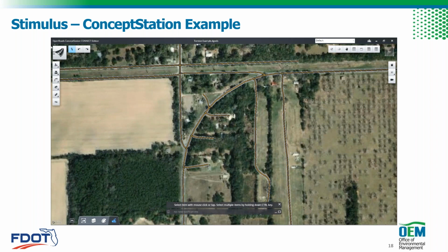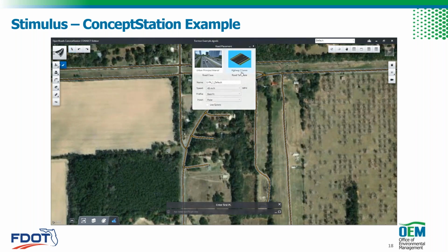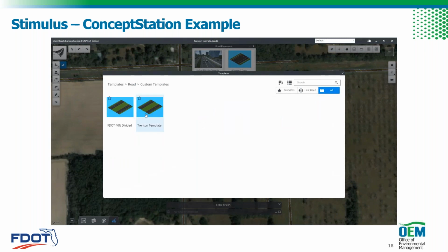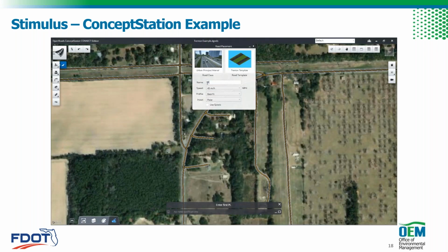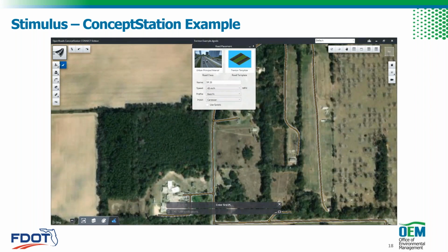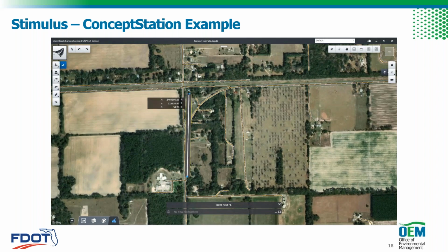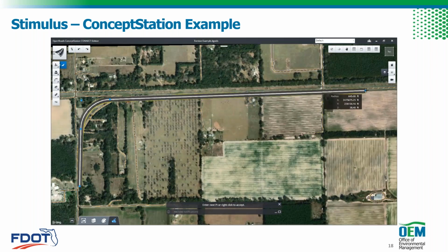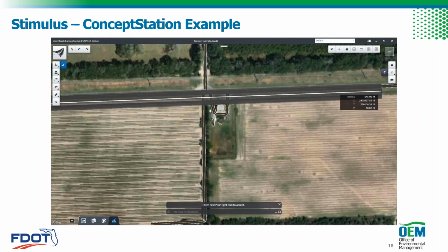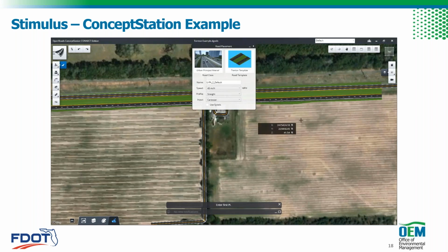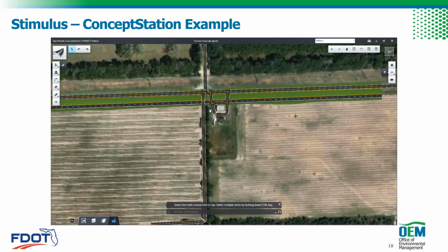After that's done, we can come in and simply choose the element that we want to place, choose a design speed. It uses the AASHTO information in order to determine your minimum horizontal curves, vertical curves, and all that information. So now I'm simply going to draw along here. And in this particular scenario, I'm imagining that the 2-lane roadway is being expanded to a 4-lane divided, right? So you can see how I'm attempting to overlap the existing there and also provide the additional 2 lanes in the opposite direction on the other side, okay?